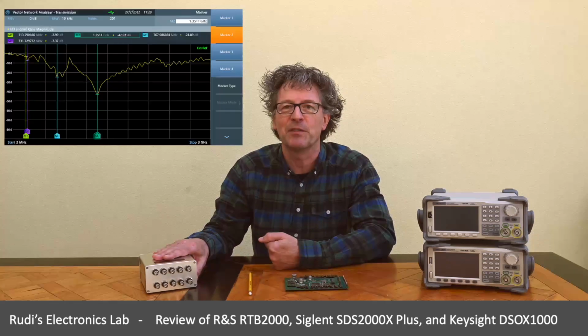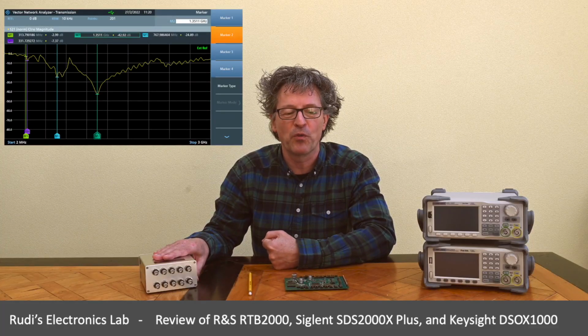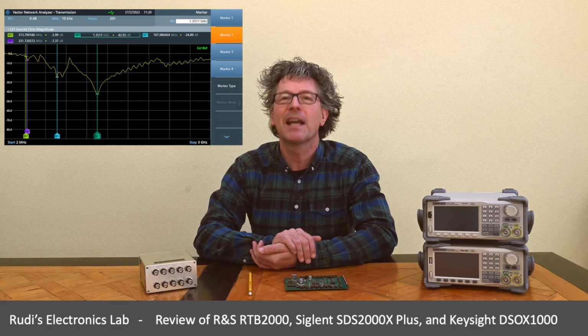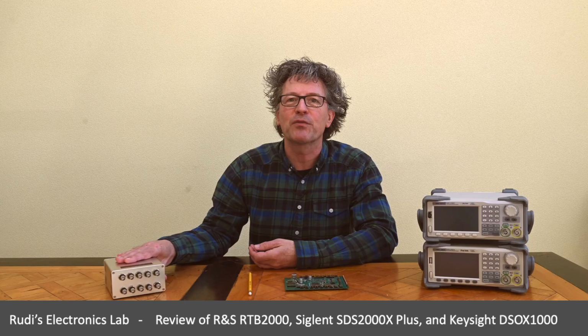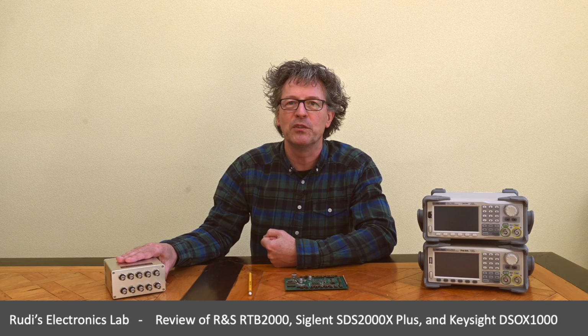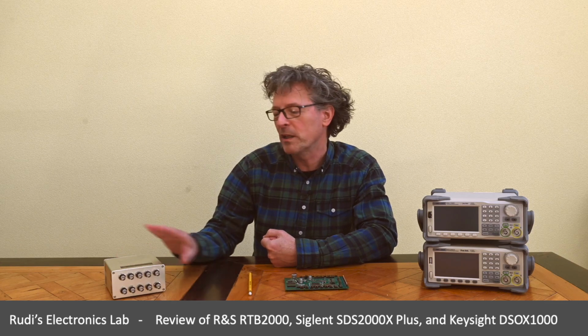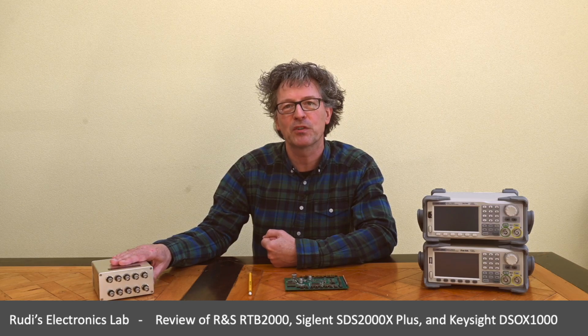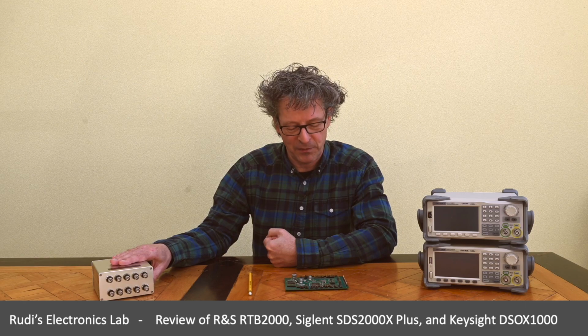However, if you would like to use this for higher frequencies, then you should not do it this way. I also looked at it up to 3 gigahertz, and we see it has big issues of attenuation at frequencies higher than 300 megahertz. The whole reason is that this is not designed at all with RF signals in mind. You really should resort to other types of designs when you're dealing with high frequency signals, and that's not what I did for this particular purpose. But for what I'm going to use it for today and for our episodes, it is going to be perfectly fine, I think. Okay, let's quickly move to the lab and look at the function generators.